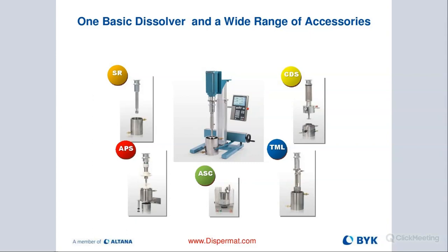You close it up with that lid, and then you are running that just as a regular media mill, depending on how small you want to go. When you're completed with the milling cycle, you can hook up an air hose. There's a socket on top of the cover of the lid, and purge your material out from the top container to the bottom container. You remove the drain plug that's in between, and then you basically can purge your slurry efficiently into this container right below.